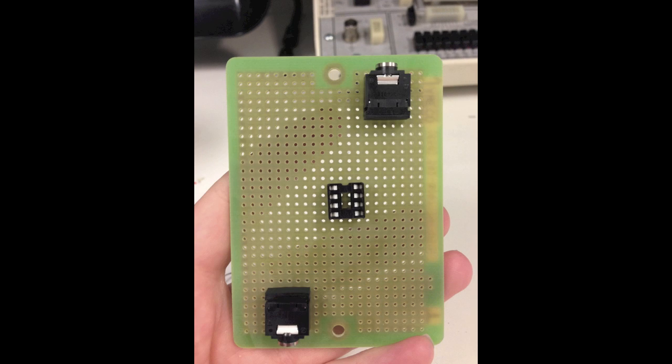So for the first part of the lab today, you're just going to place down the audio jacks and then a nice little chip holder for the op amp. This way we don't have to solder in the op amp and take it out again if something happens to it. You can just push the op amp into that little chip holder and pull it back out as many times as you need to, which is hopefully not too many times, but we do it just to be safe.